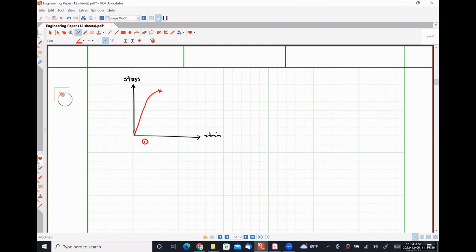We have one region. It is the elastic region. Our material might reach its fracture point before it yields and enters the plastic region. Meaning effectively, we can't deform it, right? We can elongate it to some point, so it does have some elastic properties, but it will not survive as a material with permanent deformation.